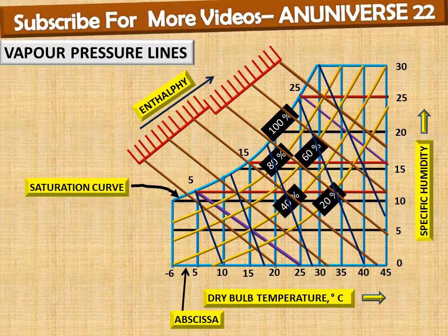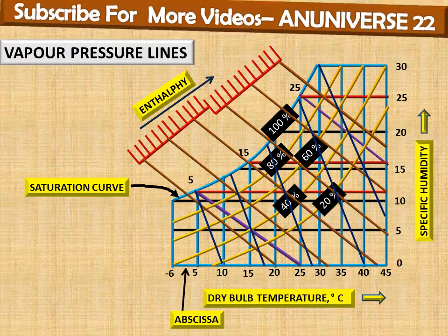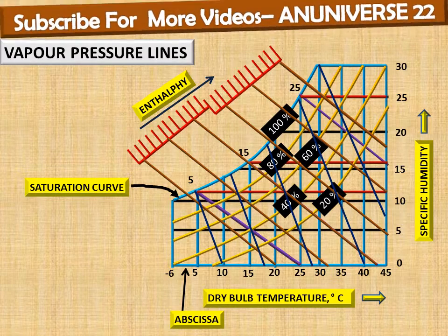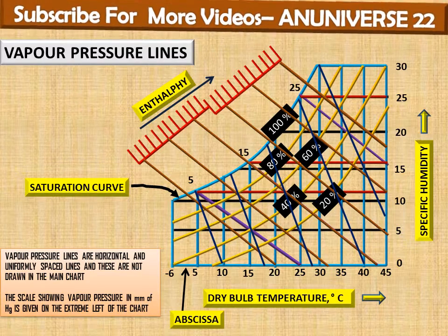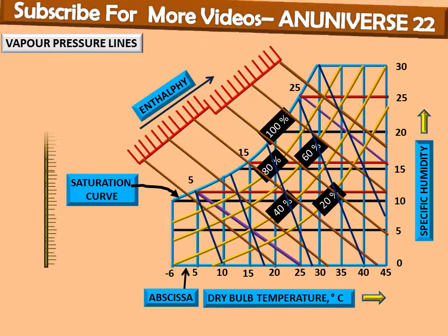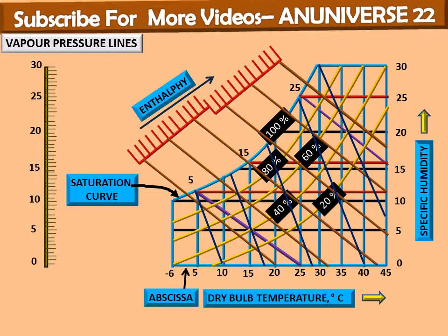And the last one is the vapor pressure line. The vapor pressure lines are horizontal and uniformly spaced lines, and these are not drawn in the main chart. As we can say, horizontal, uniformly spaced, not drawn in the main chart. The scale showing vapor pressure in mm of mercury is given on the extreme left of the chart. So this is the scale which indicates the vapor pressure line.